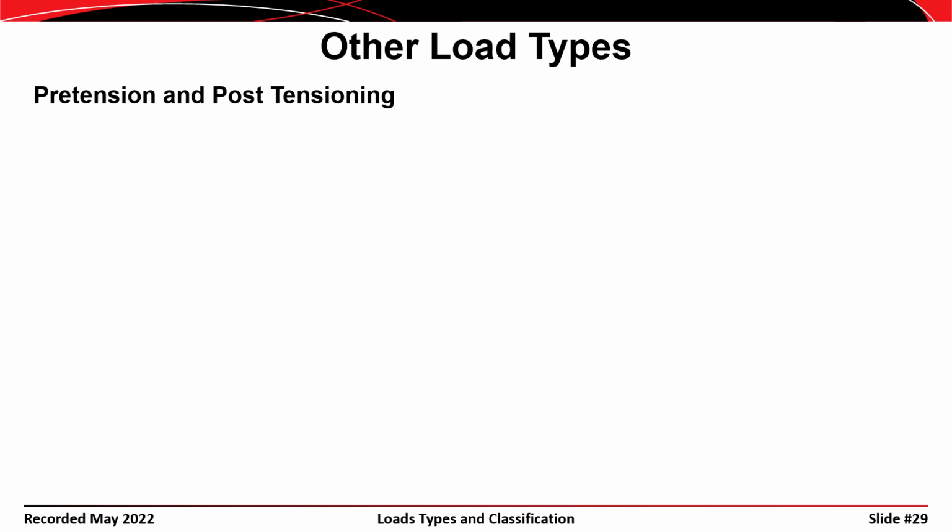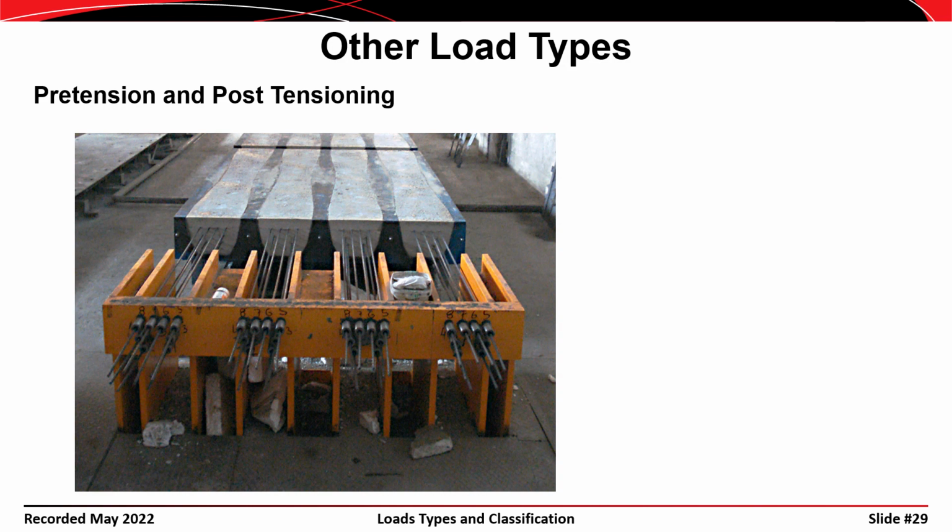There's another type of loading that warrants consideration, which are locked-in forces due to pre-tensioning and post-tensioning. These are typically for concrete, but they can be used in other types of structures as well. So with pre-tensioning, the process is that you would put cables or tendons under a high tensile stress running through a series of formworks, and then pour the concrete, let the concrete cure to some level, and then release the anchorages holding the tension in the cables. And at that point, then that tension in the cables is imparted as a compression within the concrete,